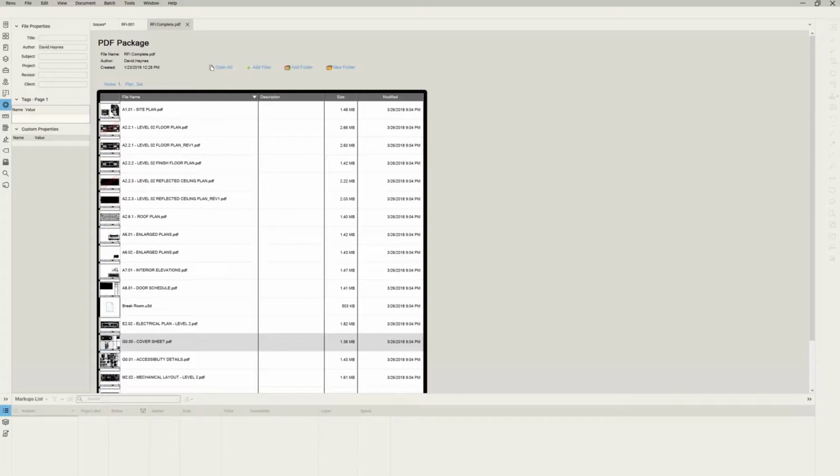If you need to give it to me again, yeah, absolutely. So the ability to add custom columns to your PDF during a Bluebeam Studio session. And so the answer for that one, if you're not aware of this, is that at this time, you cannot add any custom columns to your PDFs during a Bluebeam Studio session. So it is definitely recommended that if you do need to do custom columns, you want to add them before you upload that PDF to a session.